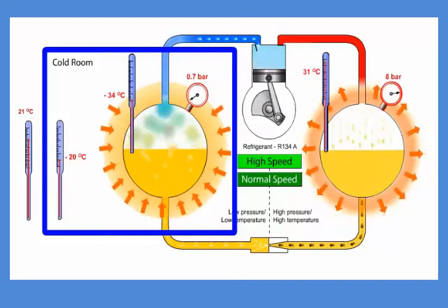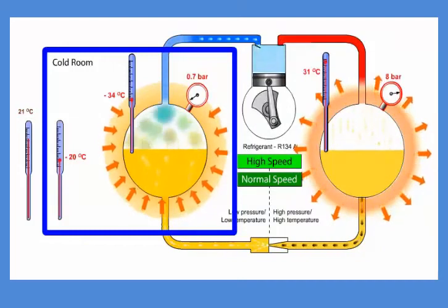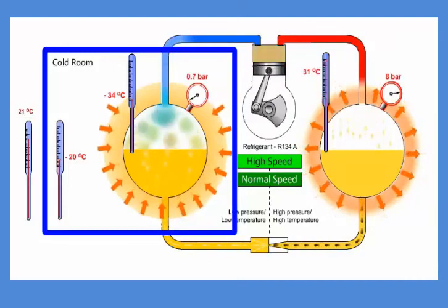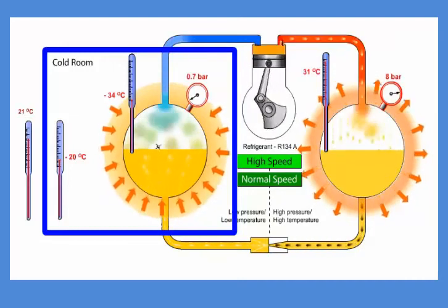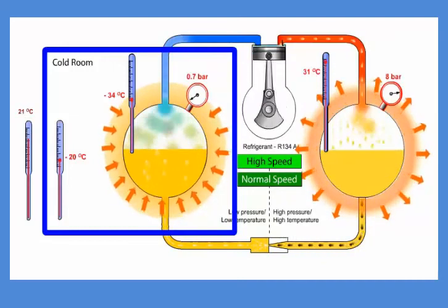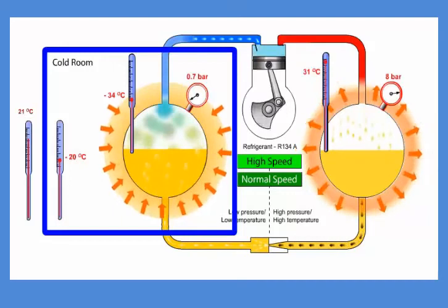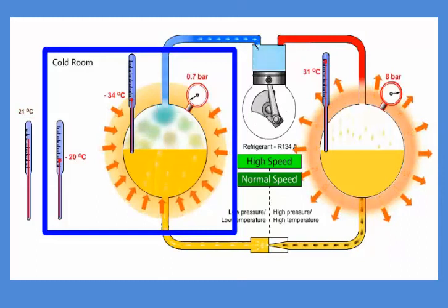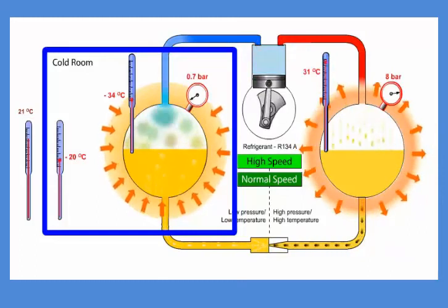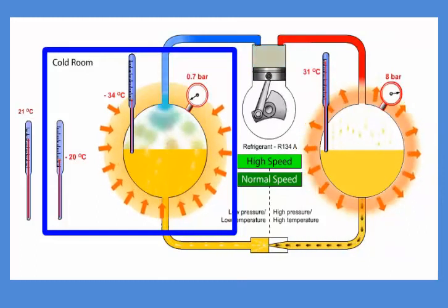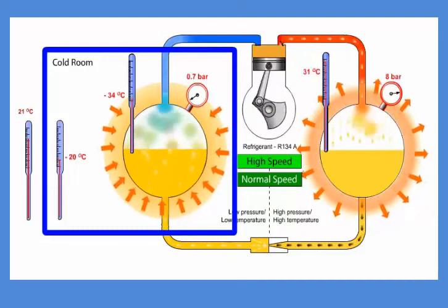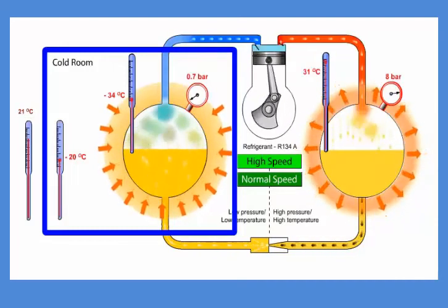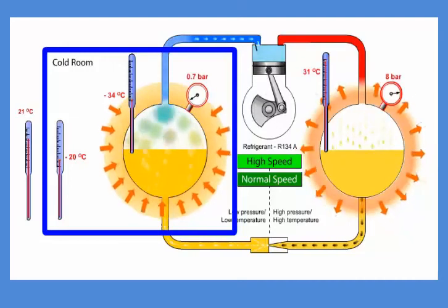When the compressor delivers more refrigerant to the condenser flask, the consequence is also that the pressure and temperature in the condenser flask go up, and the condensation process gets more violent. Now that the temperature in the flask is higher, the heat transmission to the ambient will increase because of the higher temperature difference. A new equilibrium will occur when the heat transmission energy streaming from the flask wall to the ambient is the same as the energy changing phase from vapor to liquid.